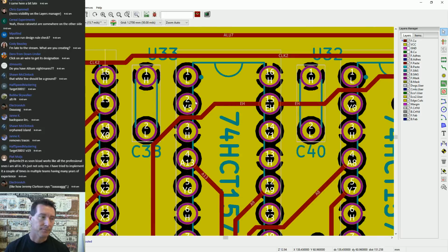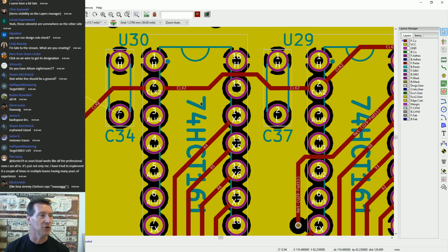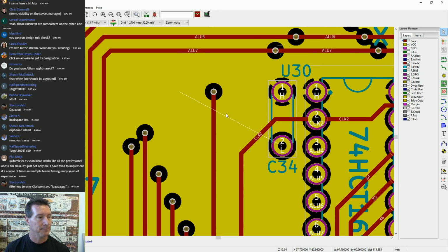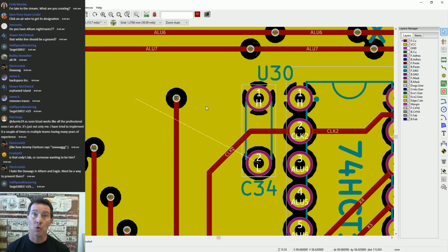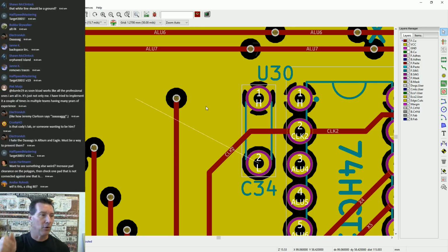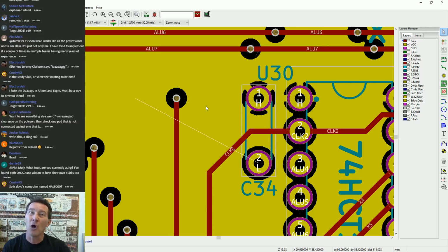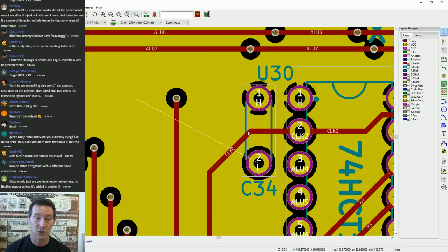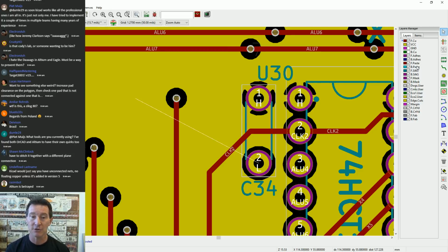So we're in basically the tidy up phase of our PCB. Let's assume that we had just routed this. And then we're at the point where we're just making sure we've connected all the nets, we've got no unconnected nets. You might, at this stage, do a DRC, and you might get a report, and you might put that on a second screen so that you have your report there, and then you just go through, and you might have 20 things that aren't connected because of that floating copper, or some other issue. And you just go through and tidy them all up until you get 0 DRC errors.